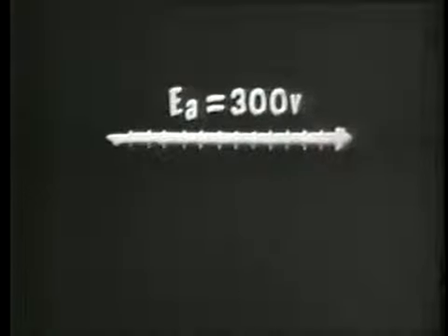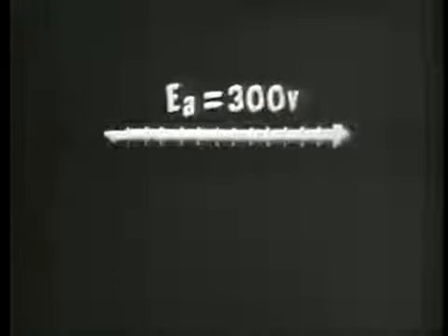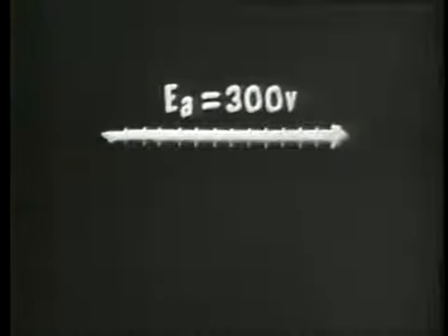Before we go ahead with the vector diagram, I'd like you to recall that when we constructed our impedance vectors, the impedance angle was a positive 53 degrees. Well, the phase angle in a reactive circuit is the same as the impedance angle, except the sign is opposite, or it would be a negative 53 degrees. Of course, we know we have an inductive circuit. We know there's going to be a current lag.